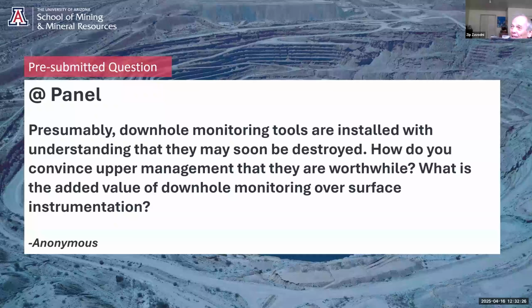And likewise, it doesn't mandate knowing the specific area or failure mode ahead of time, because the microseismic system will pick up shearing where nobody has even thought it possible. So it is an extremely valuable tool for a large-scale, long-term operation.